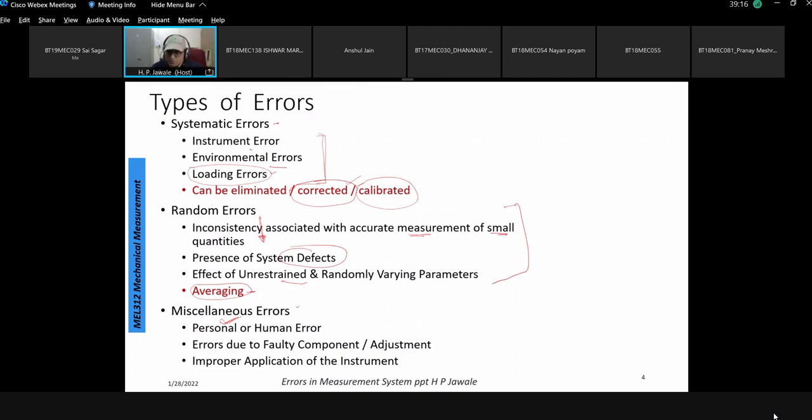Some operators may be very keen to see whether it has been restricted by some hard material. He will try to load it again, giving additional pressure to check whether the probe has touched the bottom layer or not. But it may not occur if the depth is not sufficient. So then he will take a judgment, and that judgment may again be based on the wrong criteria. So for depth measurement, this particular instrument cannot give proper answers. There can be different ways of guessing the depth.